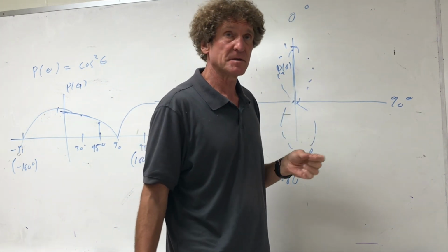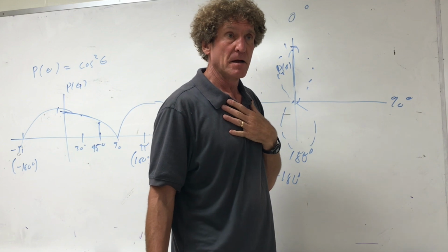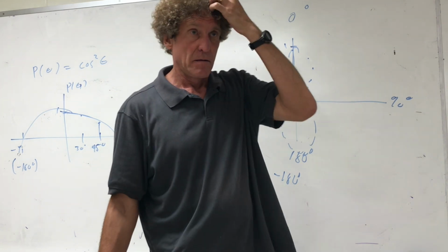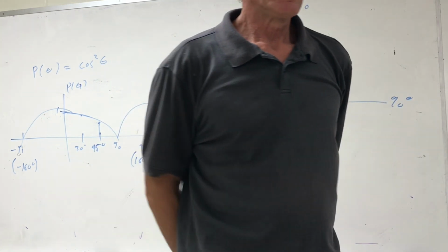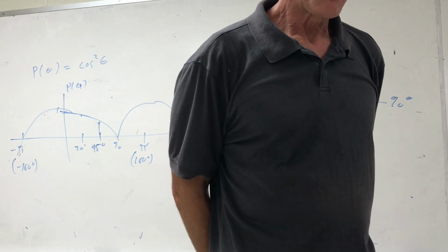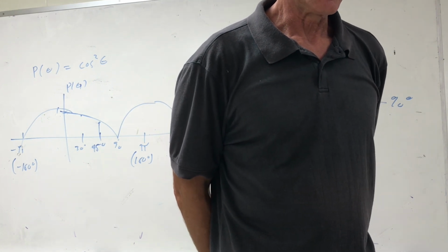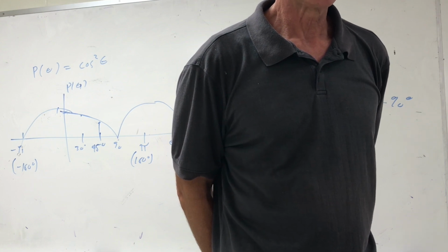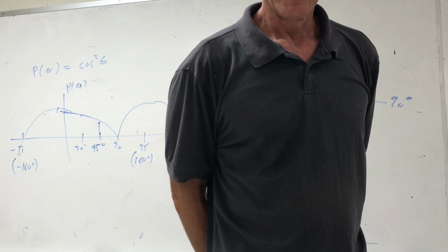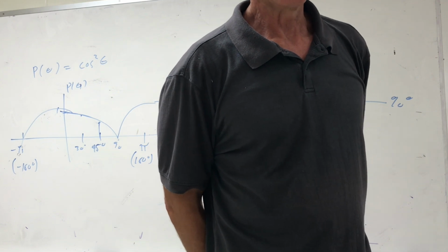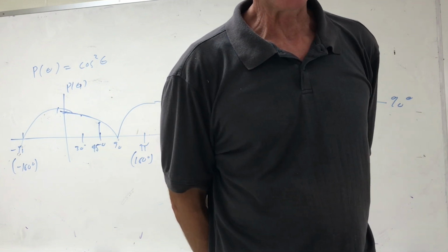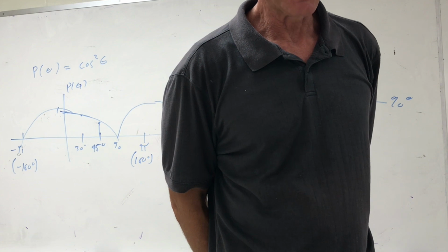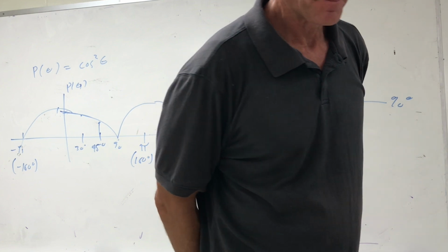And a lot of people miss that, by the way. I think I was used to the 0 being on the right, and then it goes, but that's... No, 0 is usually the vertical axis, the z direction is 0. The horizontal direction is 90 degrees. That's almost always it. Now the truth is, for a short dipole, the sine squared is a maximum at 90 degrees, so it would have a maximum value there.